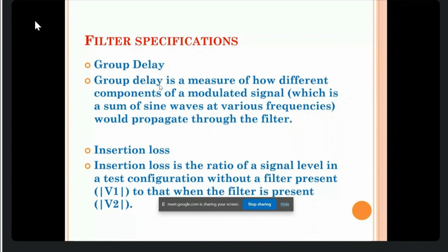For digital, if you convert the baseband signal to digital, then we modulate with ASK, FSK, PSK or QPSK. Nowadays, in satellite receiver and cable TV applications, we are using QPSK, even 64 QAM, quadrature amplitude modulation, and also 256 QAM. These are standards already available in practice, so every component that receives it should support that.